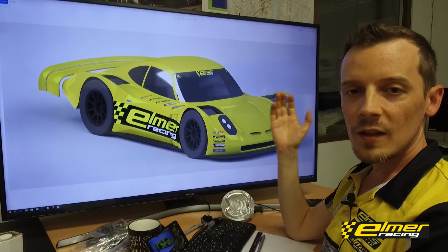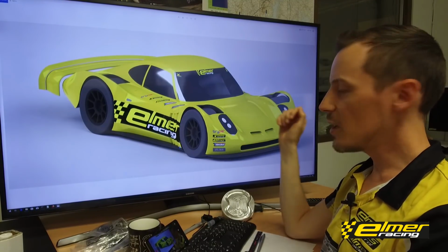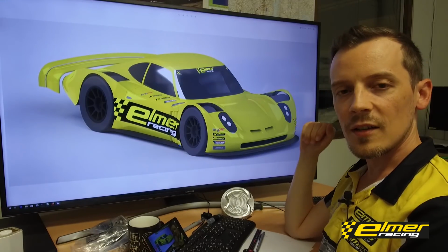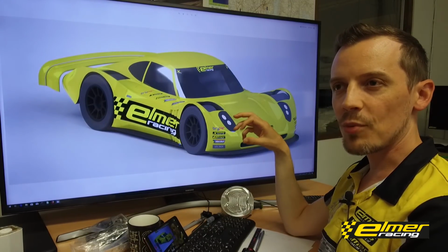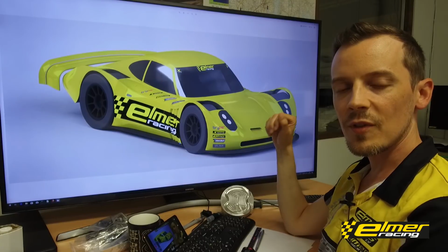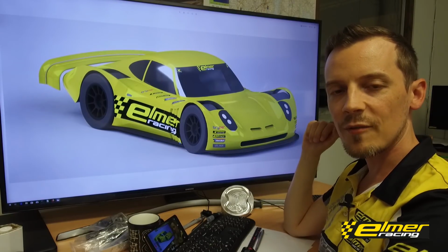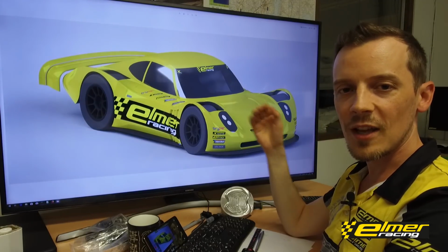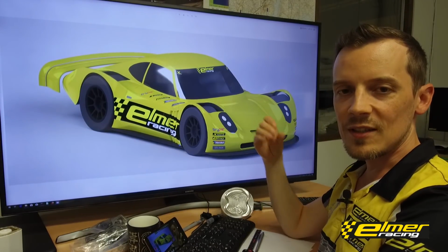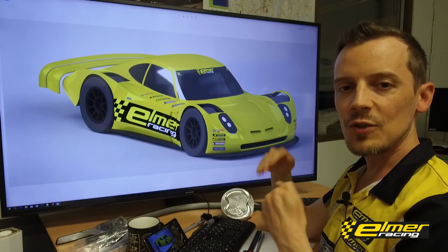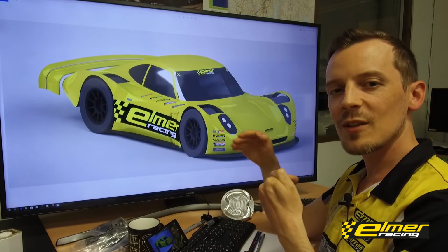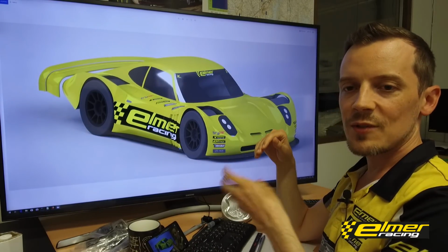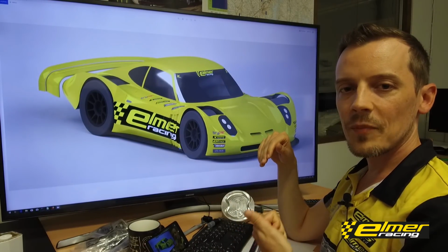The newest inclusion is Bripar, which we're working with for the brake and wheel hub upright assemblies for the er8, and looking at some custom stuff. They're also extremely helpful. We're looking at the simulation data: how much energy do we need to dissipate, in what amount of time during braking, and do we have enough time to actually cool the brakes, or do we need to transfer all of that into the mass of the brake disc?